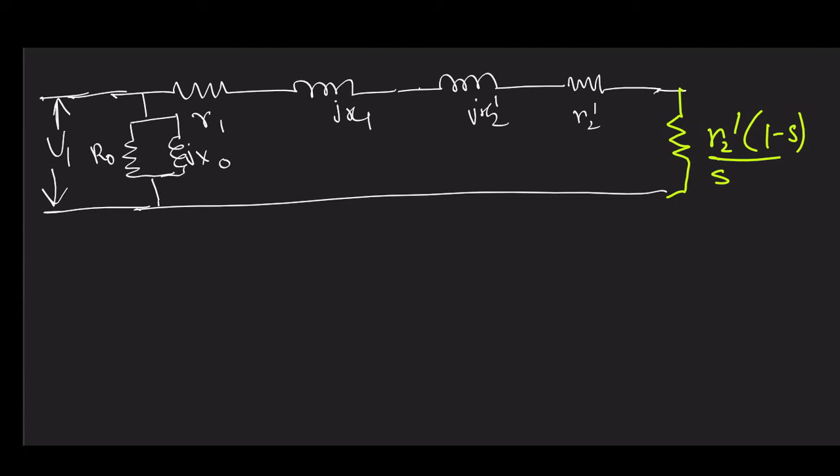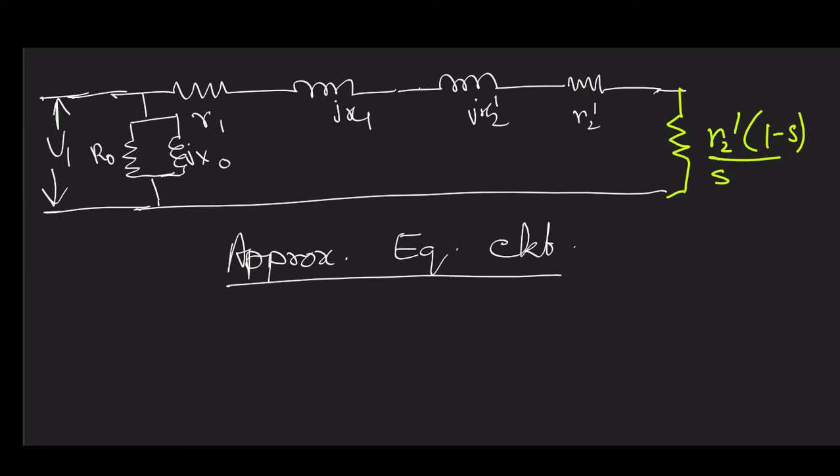And in your Indian exam, all of the problems can be solved using this approximate equivalent circuit of induction motor that comes based on the assumption that even in the worst condition, mutual flux cannot fall below 92% of unaffected mutual flux, and that is what allows us to bring this magnetizing branch ahead of the series branch.